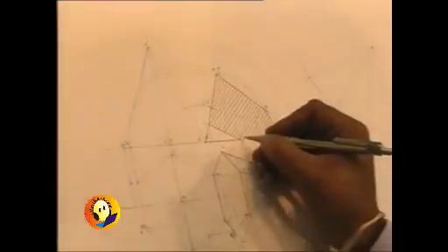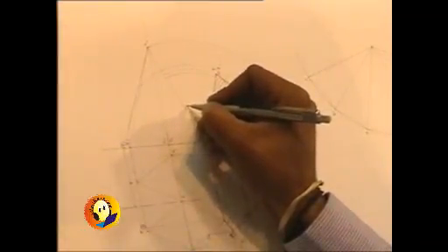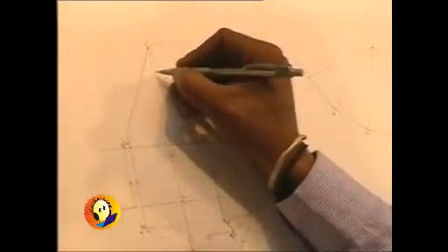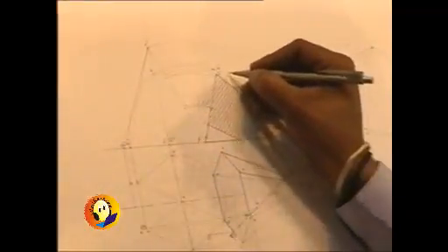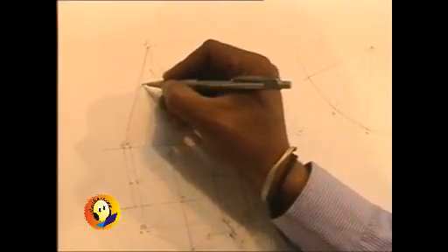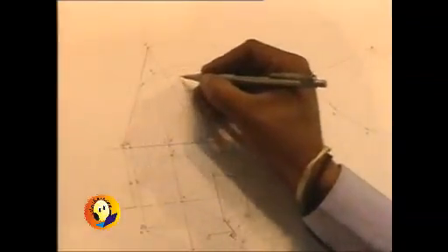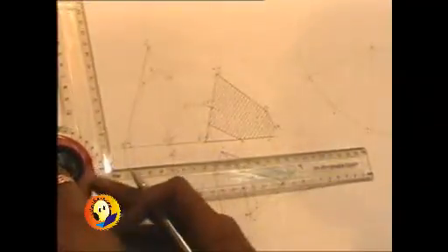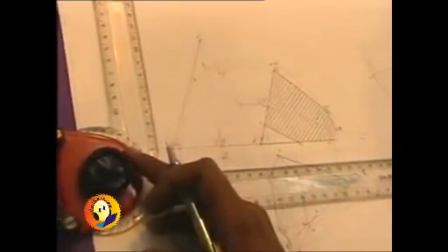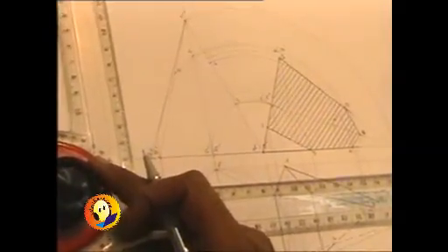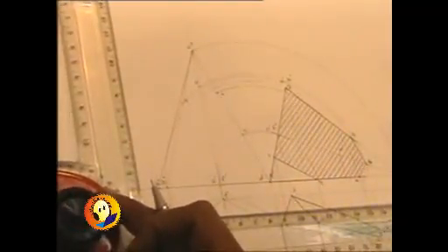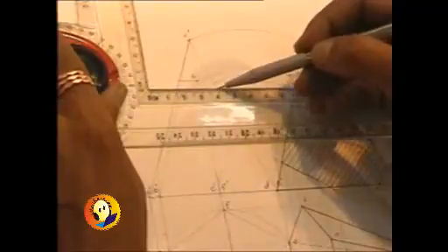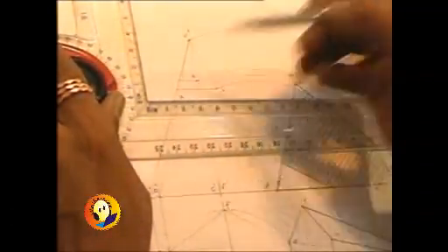So now in the elevation we have got point number 3, we have got point number 6, we have got point number 5, we have got point number 4, and point numbers 1 and 2 belong to the base. So I have transferred all the points back to the original front view where I have shown the true length. And now I am required to draw a path for each one of them up to the true length. So 6, then 4, then 5, and then finally 3. 1 and 2 are the points which belong to the base.